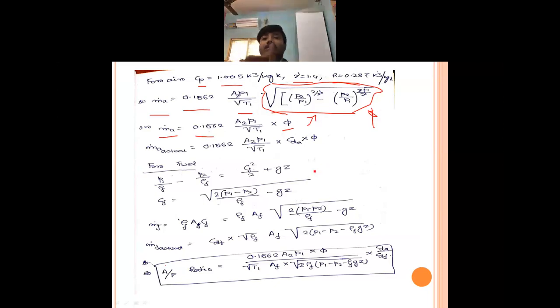Okay, now this is the theoretical mass flow rate, but we are using a venturi, so we know that for the actual cases we have to consider some correction factors. Okay, and what correction we do, that is the coefficient of discharge, because you are considering the velocity, so you have to use your fluid mechanics concept and put the coefficient of discharge value.